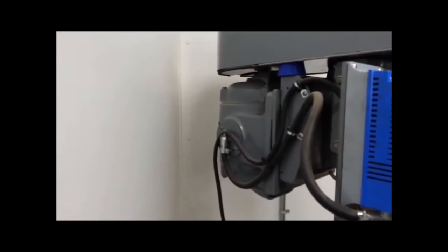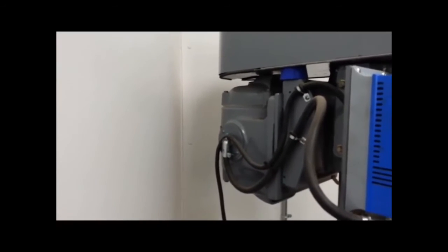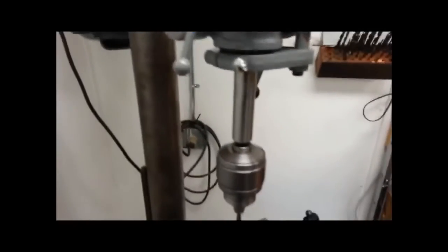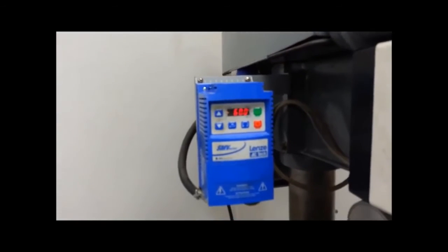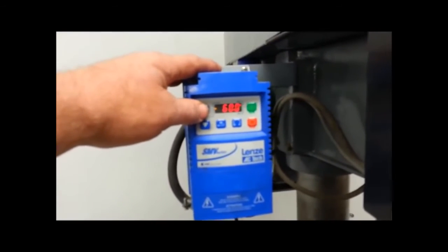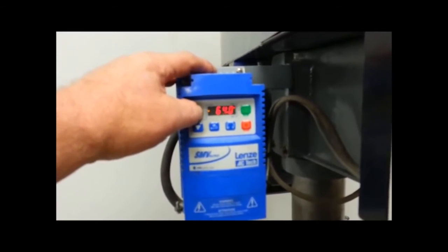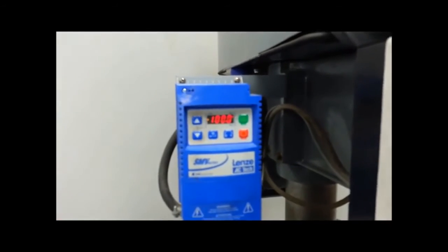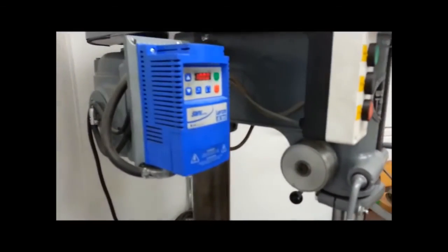It's a 4-pole. I checked it. It is a 4-pole motor, but it's only rated for 900 RPM, and I wanted to get a little more out of that. So this is actually the rated RPM at 60 hertz, but I've got this setup trimmed out, so I overdrive the motor. So I'm going to take it up. We're running it at 100 hertz right now. No troubles. I mean, I've been running this thing for quite some time.